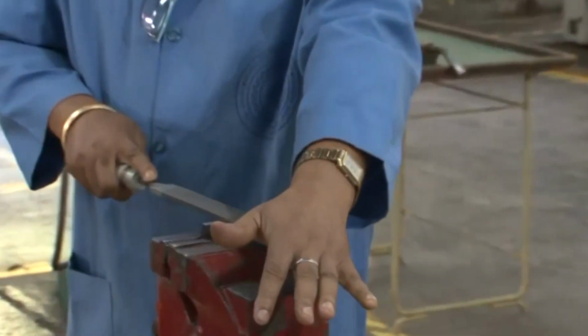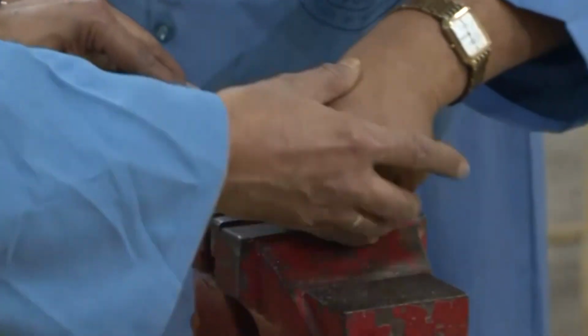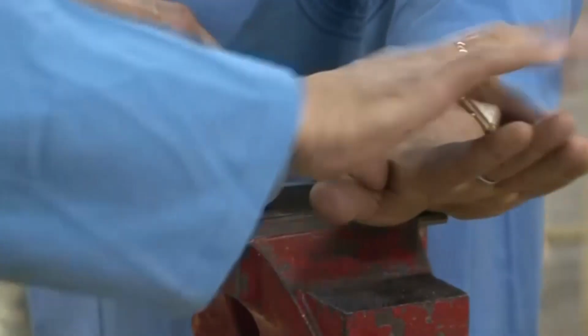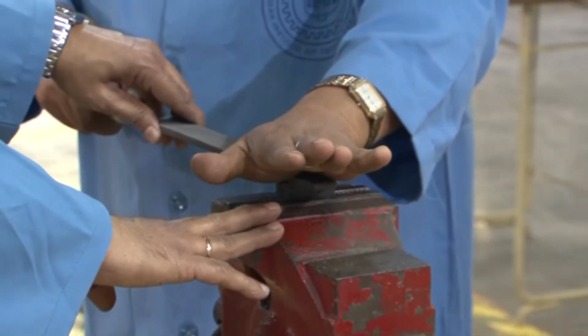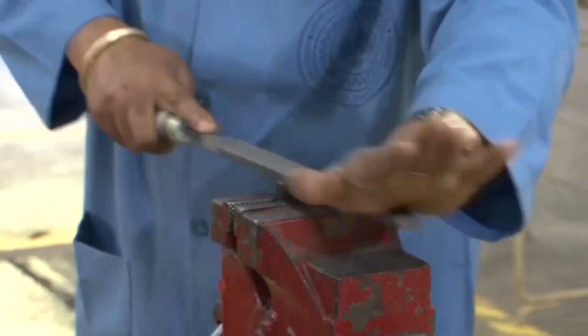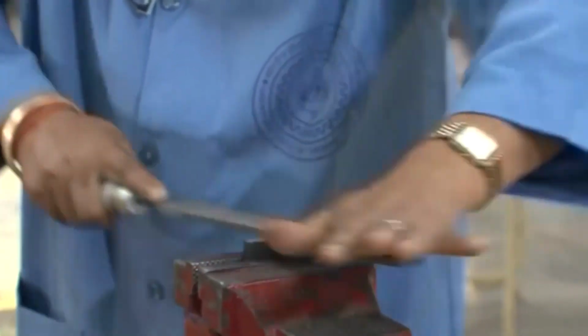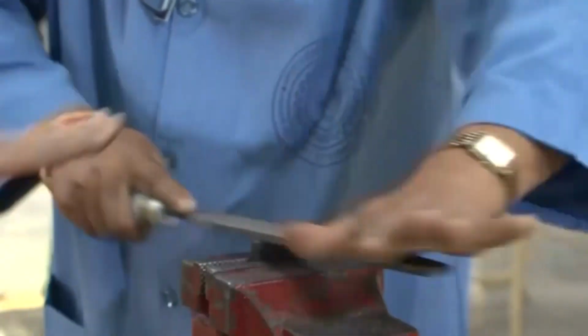So, now this is the rough file. Just mind it, for safety purposes you cannot hold it this way, because in that case you may actually hurt your hand. So, we always ask them to keep the hand like this, so that even if it slips, the hand will not be hurt, you understand that. So, this is the process that we tell the students, the way how to do that, and it has to be done absolutely on the horizontal surface. If it is done vertically, in that case you know that this will not be a flat surface, but this will be an inclined or a round shaped surface.